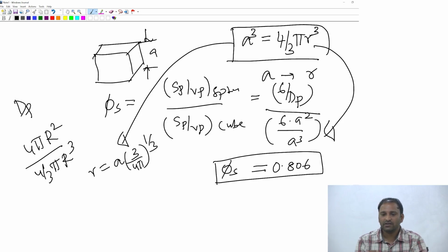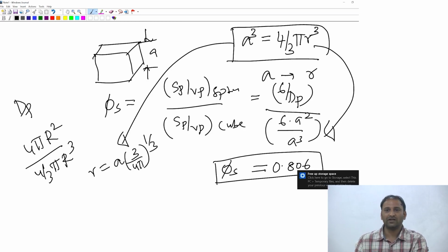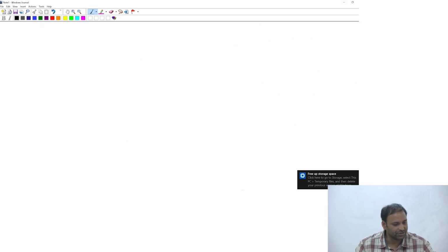So this sphericity tells you something about how to consider the shape effect. You will look at a lot of expressions which are developed for spherical particles, but the deviation from the spherical shape is accounted for by incorporating sphericity into the calculations. So in that context, this is an important parameter that you will come across in some calculations.